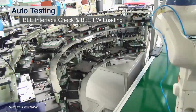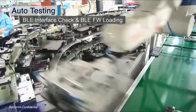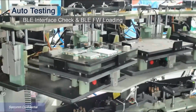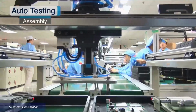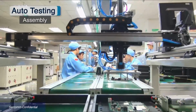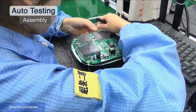Yeah, automated. So it basically takes the board, puts it in a dedicated test station. The key thing in a production line like that is to make sure that it is a constant flow, right? And some of the steps in production take 5 seconds, other steps may take 20 seconds. And when they take 20 seconds, they do it 4 times in parallel, just to make sure that everything flows at the same speed.